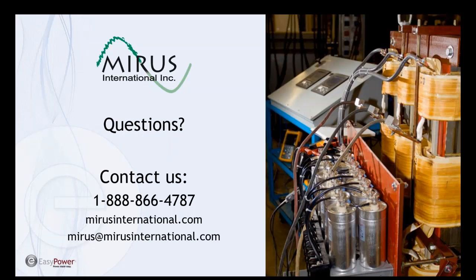An excellent question. I do have some slides that I present in other presentations and seminars. But essentially, it's the same reason why our harmonic filter is designed to have resonance below the 5th harmonic. And that is that the harmonics currently present on a power system are going to be 5th, 7th, 11th, 13th, and higher harmonics.